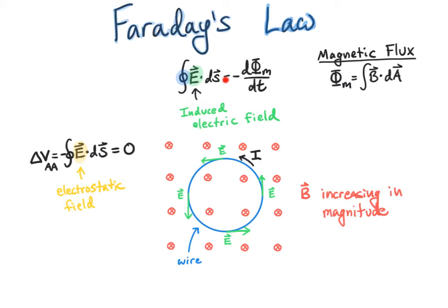So in order to simplify this integral, we're going to draw an analogy using the similarity of this integral to the integral here for voltage. We're going to define this quantity here as an induced EMF. Recall that in the context of a circuit, EMF is essentially equivalent to the concept of voltage. It's basically synonymous. As we just discussed, the induced EMF is not a voltage. However, for the purposes of analyzing the current induced in this loop of wire within our changing magnetic field, we can pretend it's a voltage.